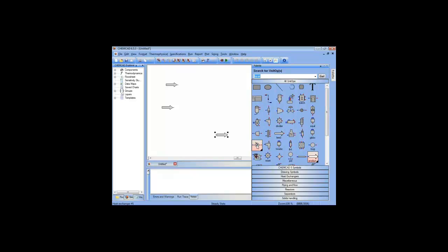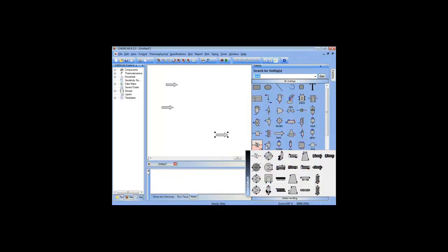For our heat exchanger, we have what we call a simple heat exchanger. Process material flows in and process material flows back out. We just simply state the temperature change, possibly enthalpy change, or a heat duty we want to add, that sort of thing. But if you notice, we've got this black corner, and the representation is that it's peeling back. There's something underneath this. If we click in that corner, we get what we call the subpalette. So there are a lot more unit op icons that we can use.